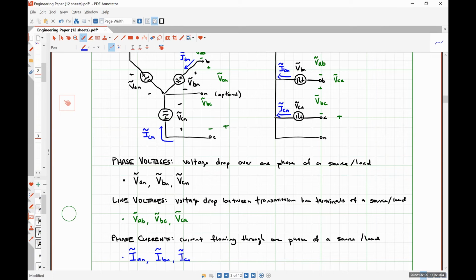Okay, so yeah, you can absolutely introduce 90-degree phase shifts using inductors and capacitors. That's how you can turn a single phase system into effectively a 4-phase system. If you have a single phase system and you tap the voltage and put a capacitor in parallel with it, that introduces a 90-degree phase shift. Then you reverse the polarity of the voltage, that introduces a 180 degree phase shift.